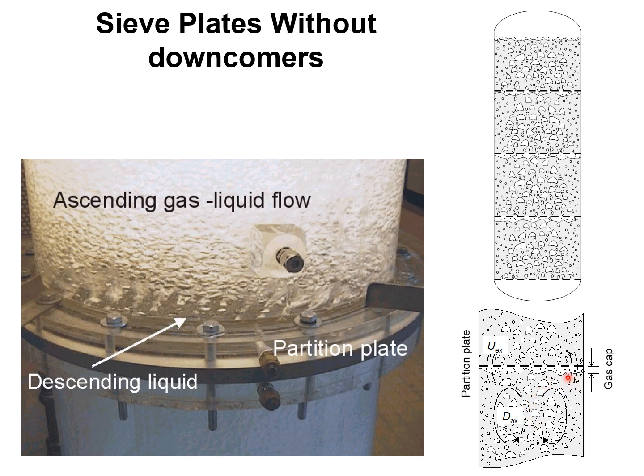What is important to note is that for gas liquid up through the column, we need to have sufficient momentum to drive the gas liquid mixture up the column, and we have the development of a gas cap below the sieve plate that builds up, and the height of the gas cap is dependent on the column diameter and the gas velocity.